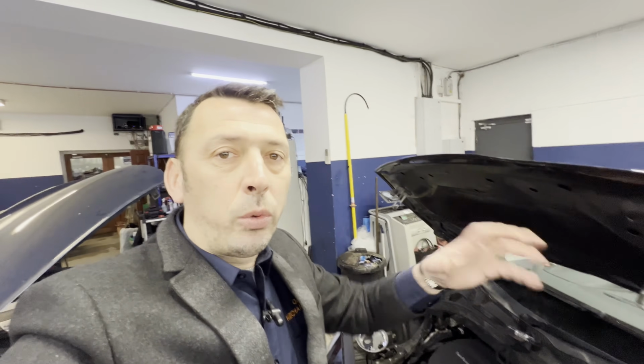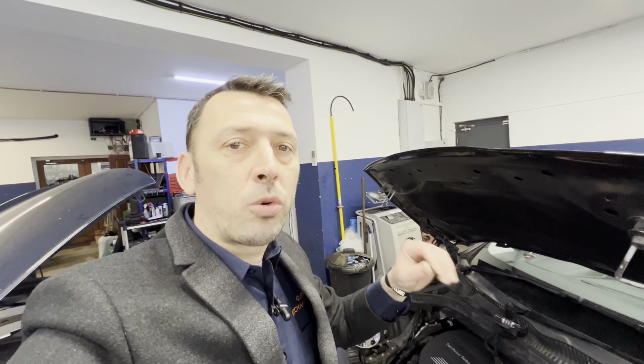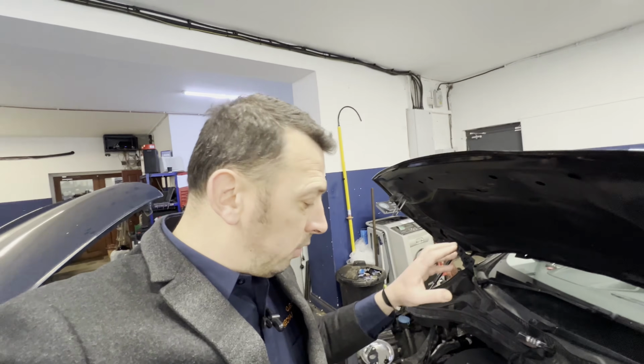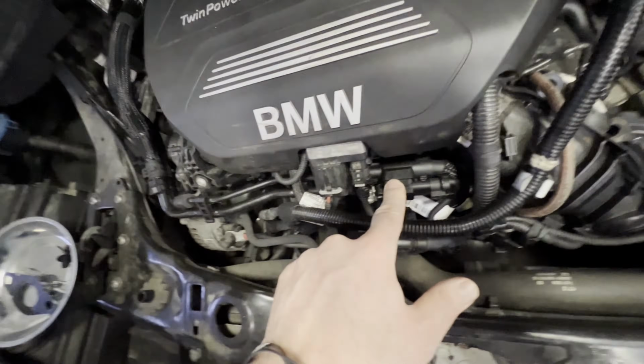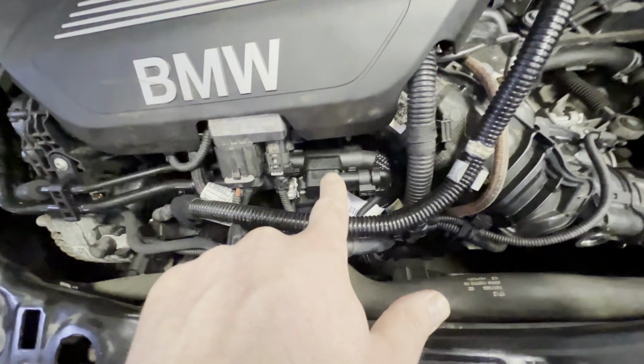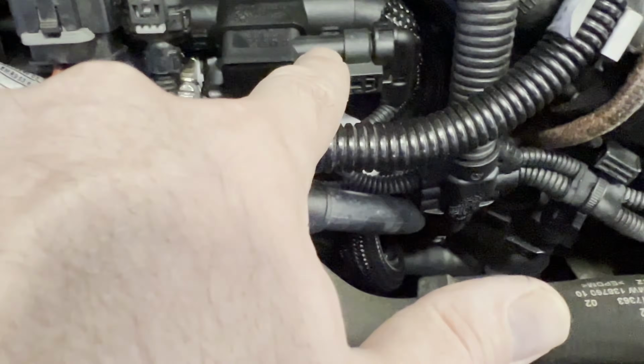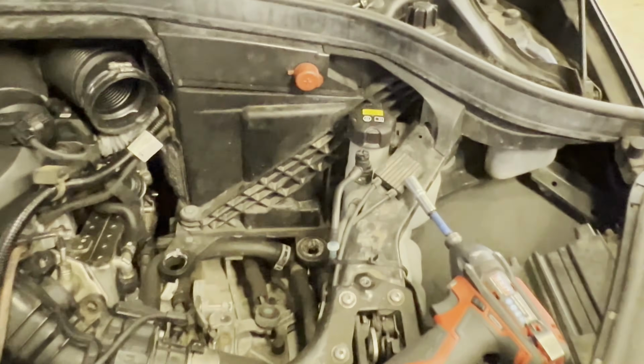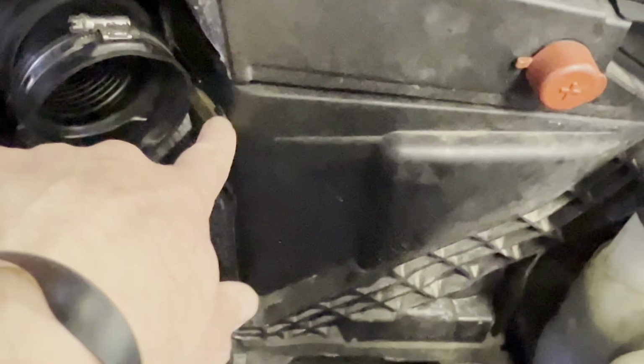It was more comprehensive. Now, to recap, the car came in running very rough. What we found is that this fuel pressure temperature sensor was defective. Through the wiring of it, there was fuel, and we also found fuel right up to the ECU, which is located here in this box.